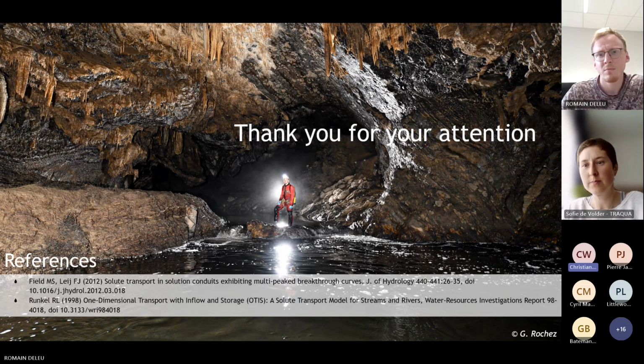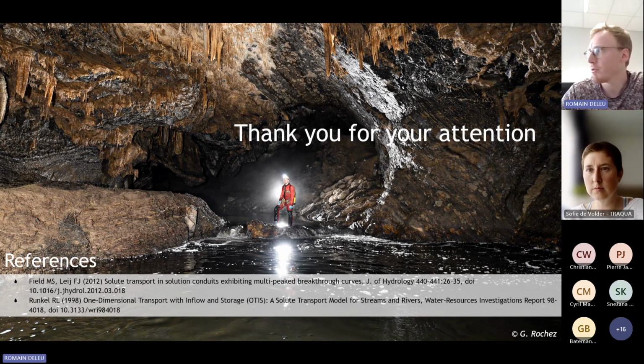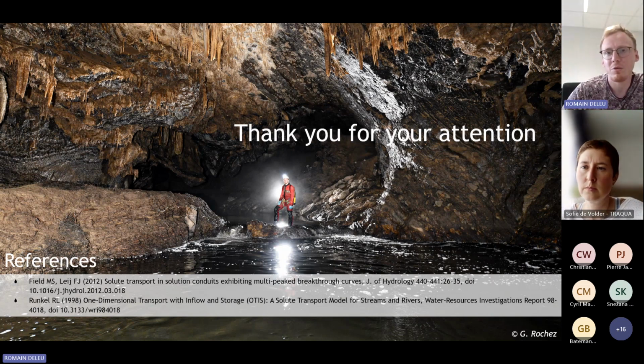You said that you could not measure the flow. What precisely was the reason, and which flow measurement method would you have used? Well, at the University of Namur, we use a Doppler effect flow rate measurement. This works for a shallow section, but the problem is that most of the sections are more than 2-3 meters deep. So this was kind of difficult. We tried, but it's difficult with a boat to measure the flow rate.